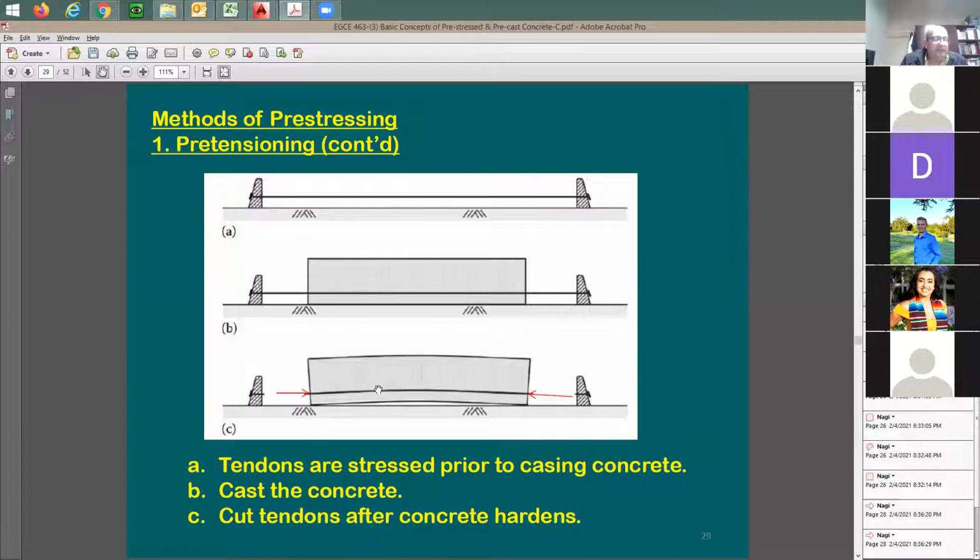It means axial load. Now, is this concentric or eccentric? Say here's the center line, right? It's the centroid line. Is this eccentric or concentric? Eccentric. So it means that as if you're going to have here a point load and a moment. Now you have combined loading. This is why I said combined loading is going to be very important. We need to study the stress, and you're going to see that this is really important, right?